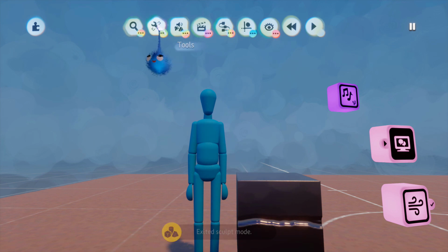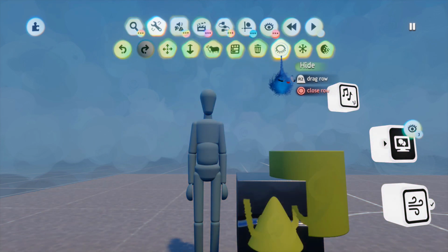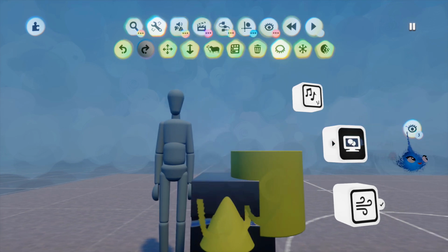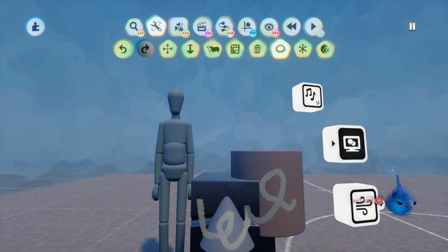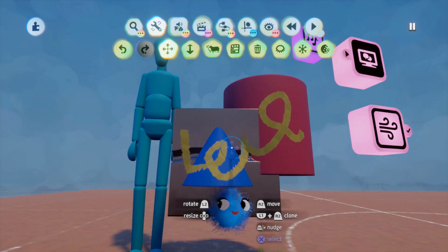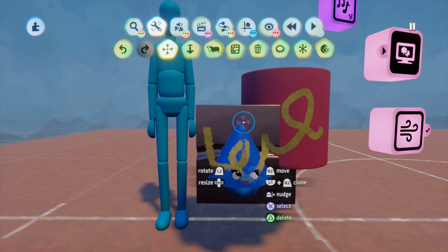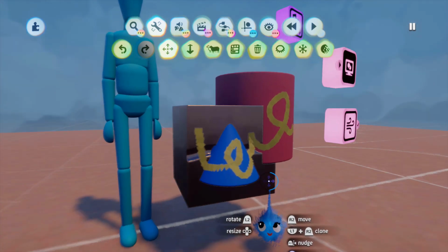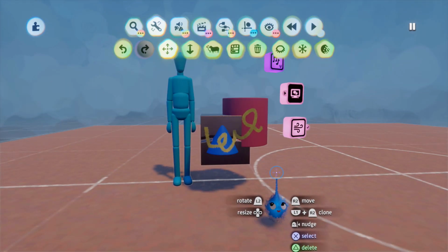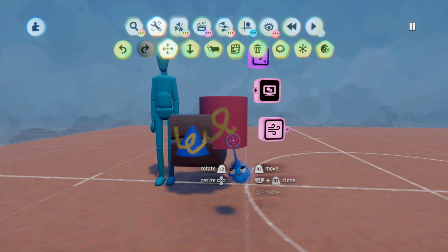You go back into tool mode. I want everything to come back, so I press on the tool, and as you can see over here, you've got this unhide all. It tells you how many objects you've got hidden currently, and you can just unhide them, and there we're back. And now you can see I've sculpted into this at the back of these objects without any problem at all. What it's really useful for is for things like snap to surface with the paint.